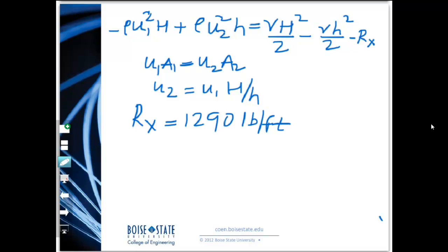Okay, so you can see based on the previous answer, it's considerably less, almost less than 50%, right? So that would mean that it takes considerably less force to have the sluice gate in place when it is opened because there is some mass flow rate out of the system, or out of the control volume. Okay, so this is a nice little example of an application of chapter 2 principles and what we learned in this chapter.